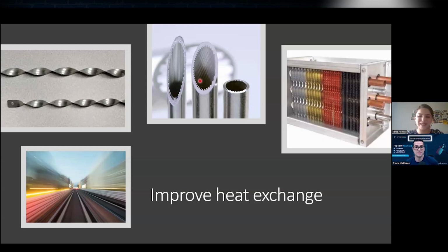I don't know how you call it in English. Yeah, grooved inside all the perimeter of the internal diameter of the pipe. Some are straight and some are at an angle. So that must mean something different. Yes, this is very important because it helps us to increase the velocity and also the turbulence.